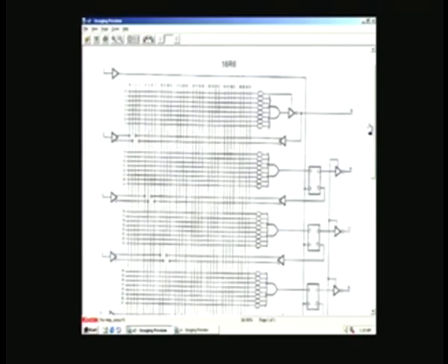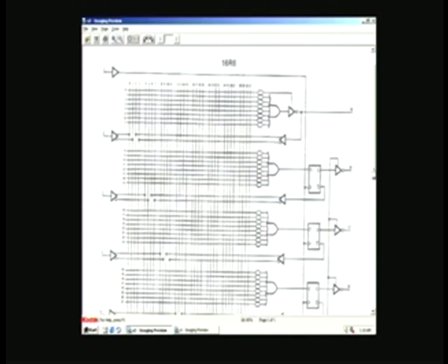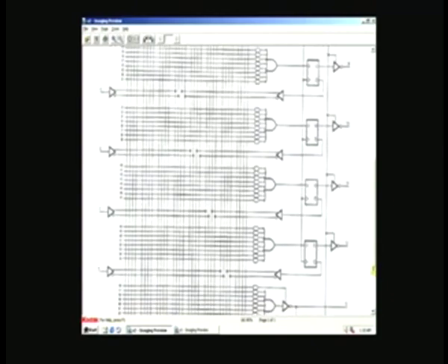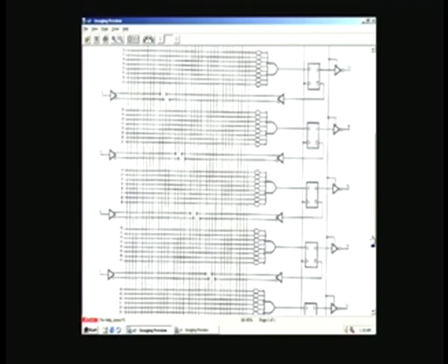Actually the input number 1 is not counted as a clock. So input 2 to 9 are 8 inputs, 6 registers, 14 and another 2 IO inputs. There are 6 registers as I already showed you. Let us see how to fit this design into this device.